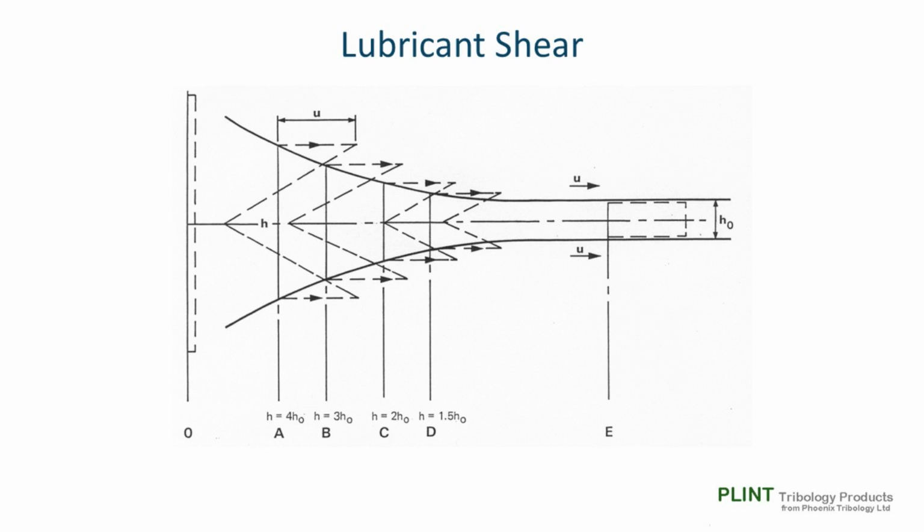The film thickness h in an elastohydrodynamic contact is largely determined by processes taking place in the approach or inlet zone to the contact zone proper. In this region, lubricant entering the contact has been subjected to intense shear, if at only moderate pressures. Then, on its passage into the contact, further shear at a lower rate but increasing pressure.